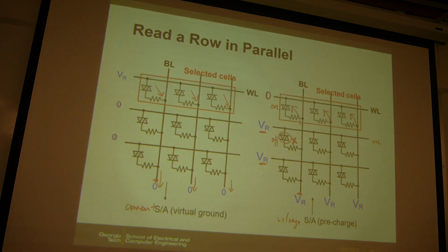Yes. So that's why we need this selector. So if you think about here, then this voltage decaying, that means this VR will be smaller than this VR. Then you will have some current contribute into this. Then that's not good, okay? Because you only want to read this cell, the readout current only depends on that selected cell. You don't want the other rows to interfere with this. So that's why we need the selector. We will discuss that.